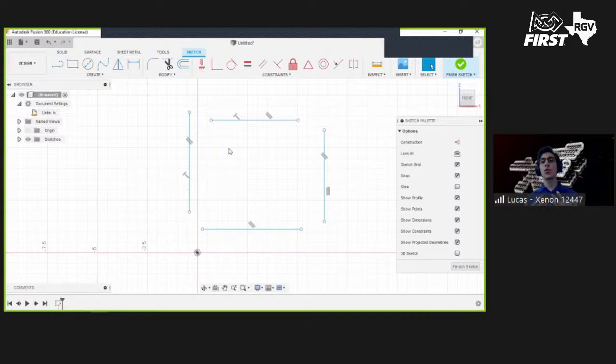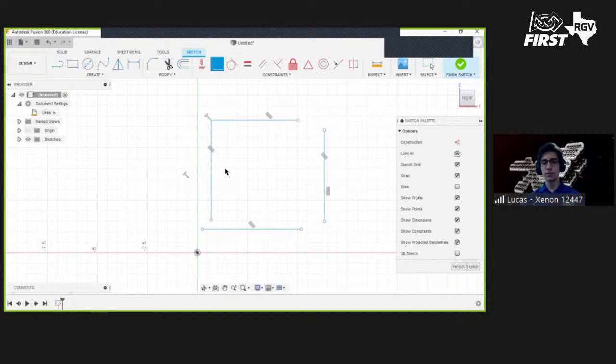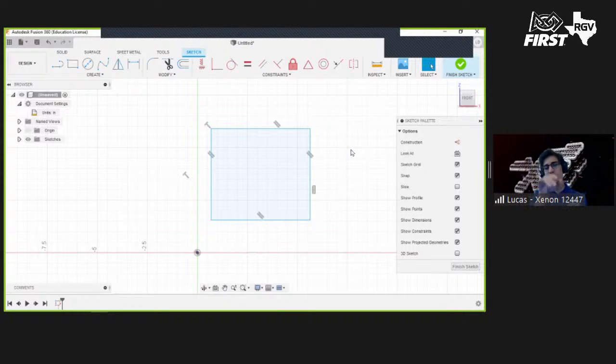Well, I would use a coincident constraint like we just talked about. This coincident constraint, I can click that, click one vertex, another vertex there, and boom, they're touching. I click one vertex here, one here, they're touching. Do the same with each side, and there is our rectangle. So notice we have 4 parallel constraints. We have 1 vertical constraint. We have 2 perpendicular constraints.